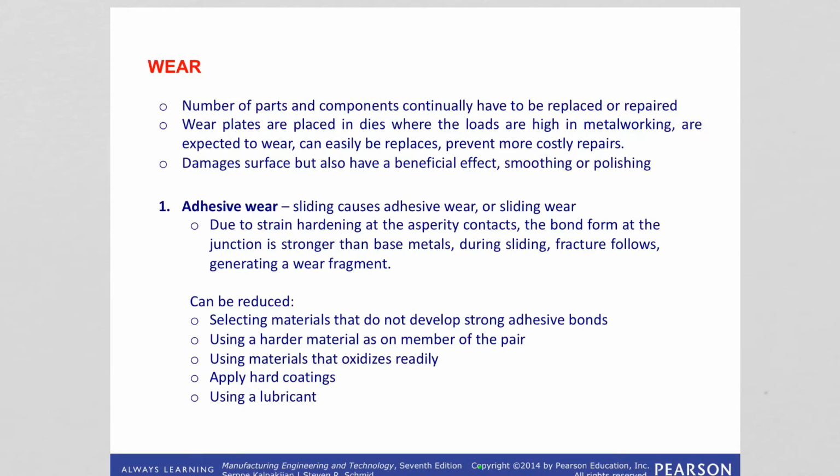Use a harder material as one member of the pair. Use materials that oxidize more readily, because this will create a protective film. Apply hard coatings, or coat one surface with a softer material with low shear strength, such as thin silver or lead, or use an appropriate lubricant.